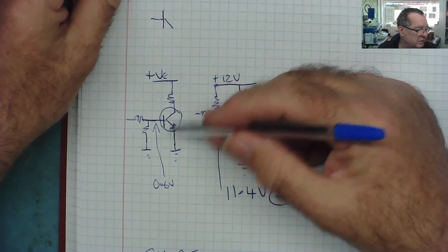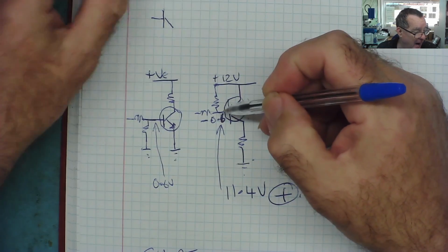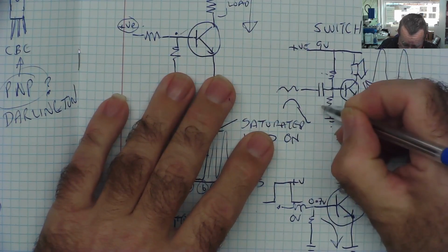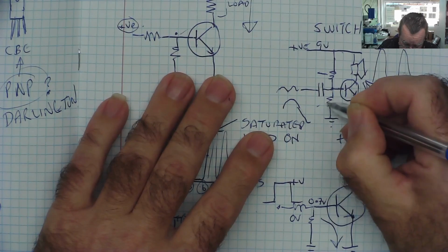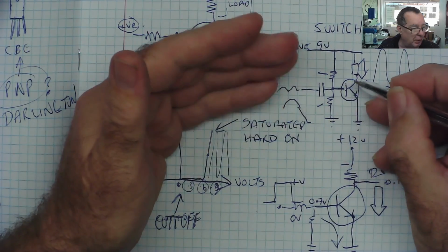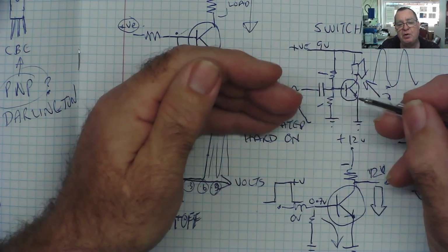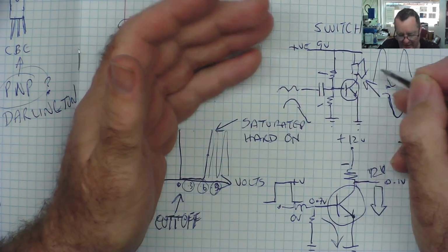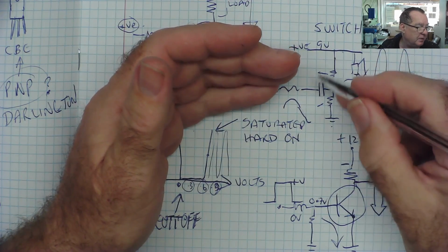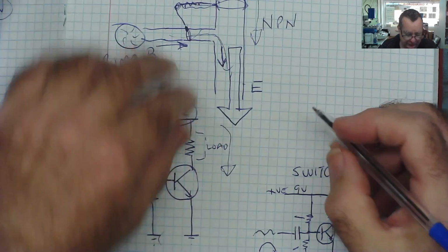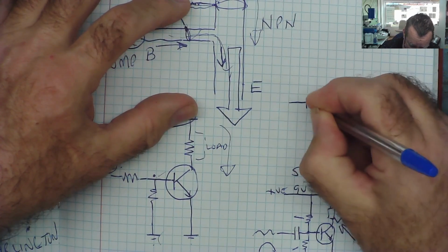Transistors can fail, especially in amplifier circuits again, where, I'll choose another page, this one, there's a problem with these resistors. These are called bias resistors. The idea of the bias is that it holds the transistor in its quiescent state, partially conducting, or just on the point where it will start conducting. And problems with these bias resistors can affect the way the transistor works if it's not biased properly. So that's something you need to bear in mind. And the other one is that you often find transistors connected like this type of circuit.